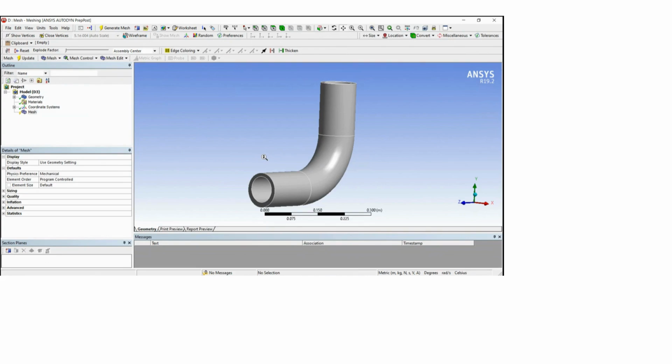The step meshing on this part. Now let's see how we can apply the step meshing. First, how can we check on which geometry we can apply the step meshing? In Ansys Meshing we have criteria to see which body is a separable body. Separable body means where we can apply the step meshing. So on this complete body we can apply the step meshing.